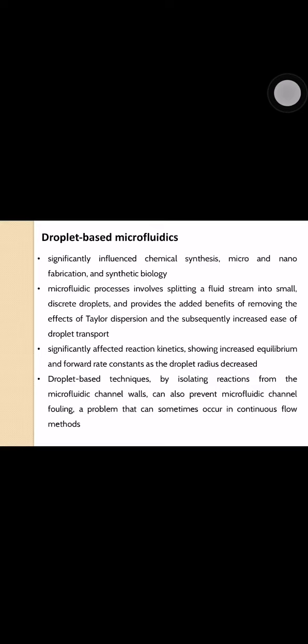Droplet based microfluidics. The more recent development of droplet based microfluidics has significantly influenced chemical synthesis, micro and nano fabrication, and synthesizing biologicals. This alternative method of microfluidic processing involves splitting a fluid stream into small discrete droplets and provides the added benefit of removing the effects of Taylor dispersion and the subsequent increase in droplet transport.